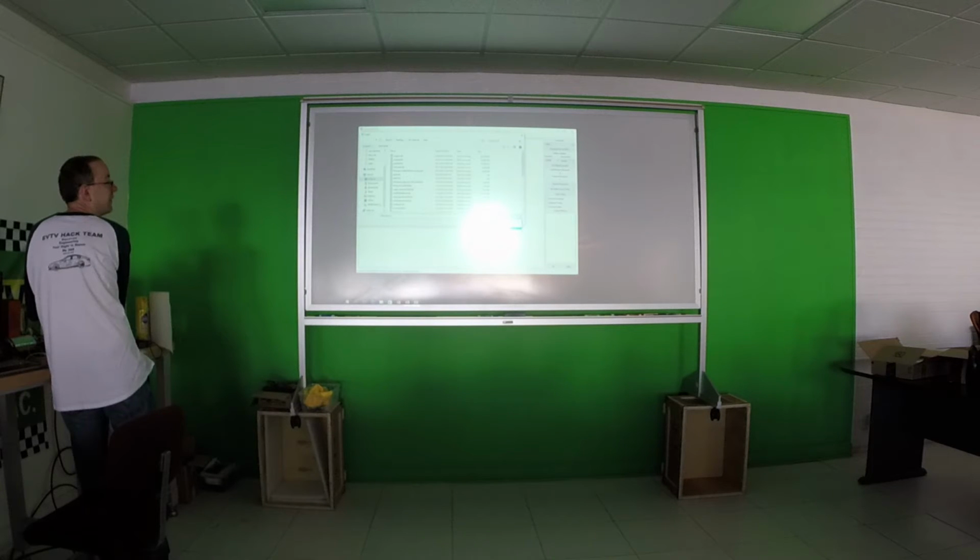Busmaster is kind of a competitor, an open source reverse, well, not really a reverse engineering tool. It's essentially an open source CAN analyzer. It's kind of hard to use. Some people have Microchip capture cards, and we can load and save in that. But the default formats here are CRTD and GVRET format. I have the defaults for most things set to CRTD.